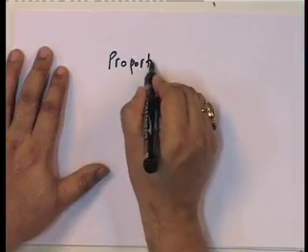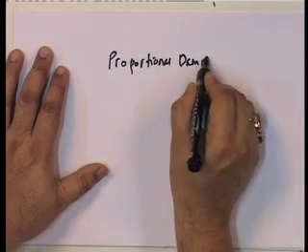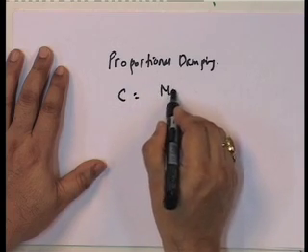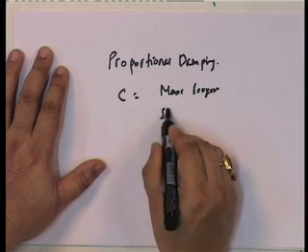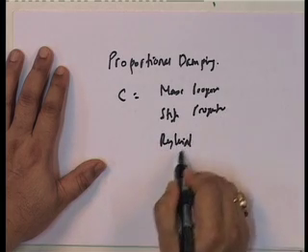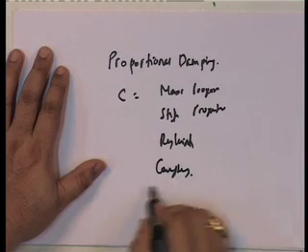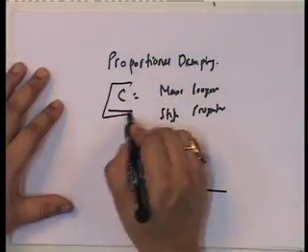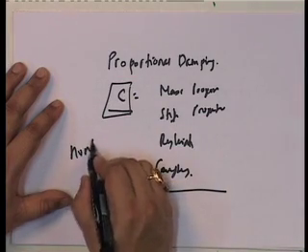Only Caughey damping will give you the same result. Please understand that. Therefore, the whole question of proportional damping, and the fact that your C is mass proportional, stiffness proportional, Rayleigh or Caughey, is relevant only if you have a system where you require C, which is when you go nonlinear.